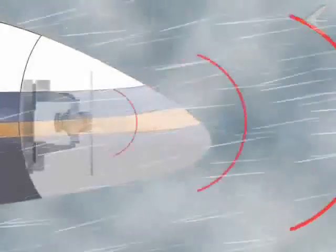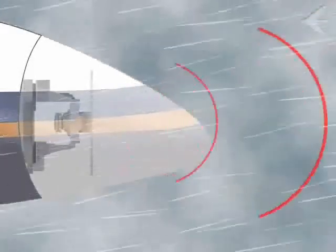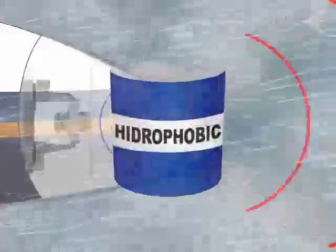Now we are flying through a heavy rainfall at a specific altitude and speed, and the radar display disappears. This is not a radar failure. It happens because the water flows over the radome and covers it completely with a water film. This water film, or vapor, generated by the airplane speed can block the radar emission, and a red or black display can be shown. To avoid this problem, apply some hydrophobic coating product. Dirt and grease can impair the radar performance too. An inspection before flight can avoid and save much headache.